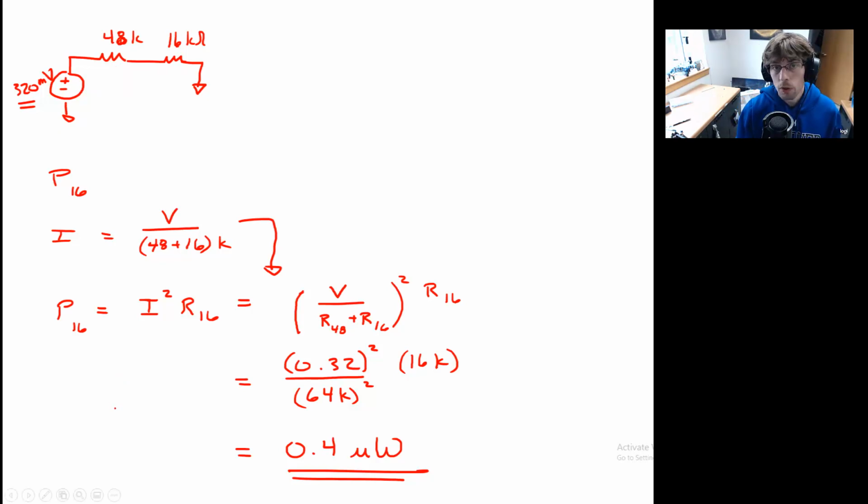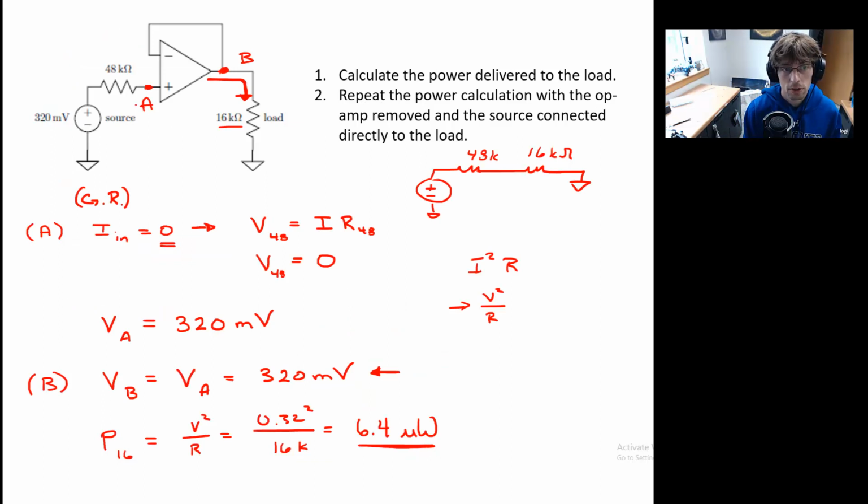Just to let you know, this form of a circuit where you do not have a resistor between the output and the inverting input is called a follower circuit. In other words, the output of the op-amp follows whatever the input is.